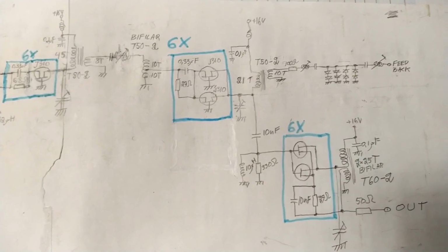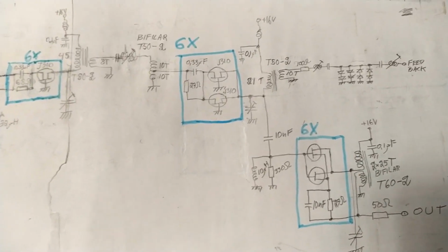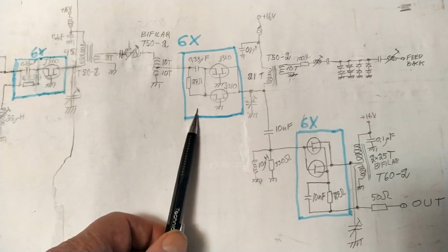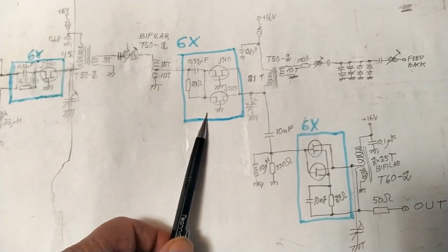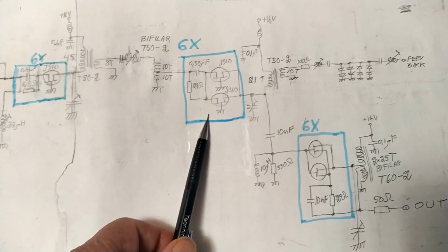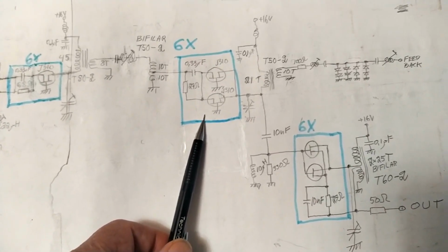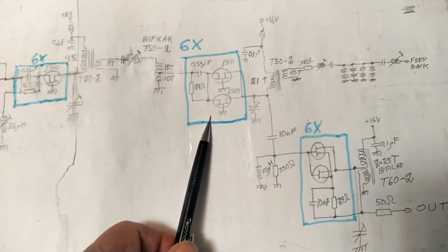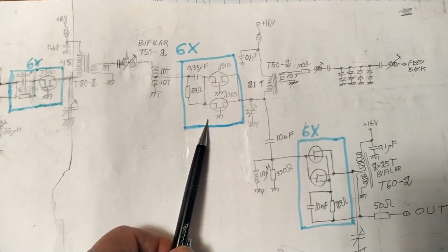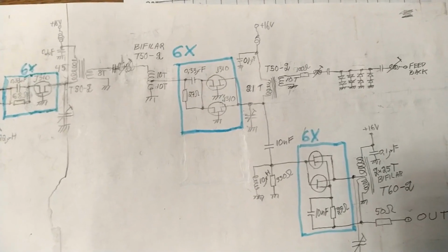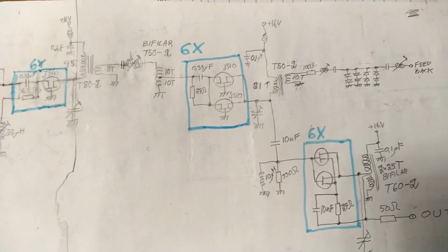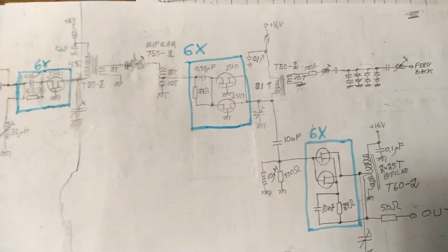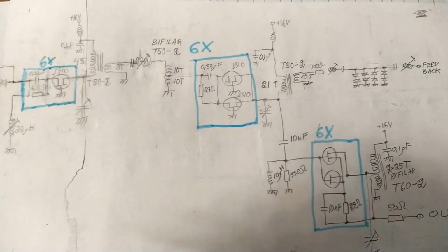So what I will start to do now is to replace these transistors by bipolars that should have smaller flicker noise, particularly since I will use fairly large emitter resistors to get current feedback to keep the current constant through the transistors.